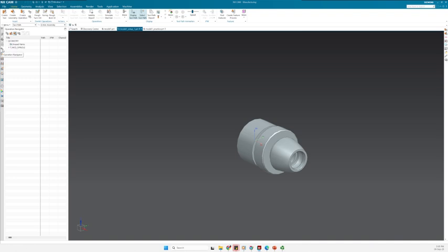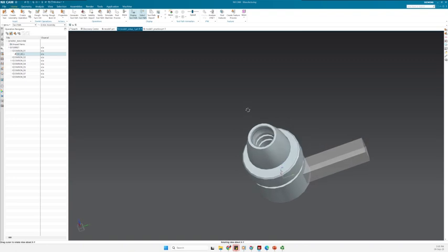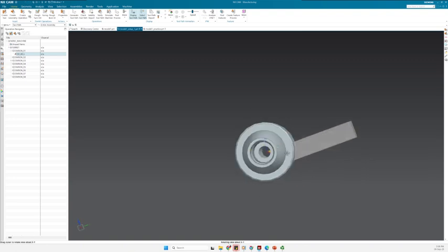Operation Navigator. The Operation Navigator itself has 4 main tabs. The first one is the Program Order View. Program Order View is currently empty, but this is something that will be filled up a little bit, and we will come back to it later on. Then we have the Machine Tool View. So this is our turret. Currently, it is automatically predefined with Station 1 for an outside diameter tool, which is now colliding. It is now inside here.